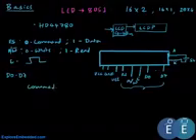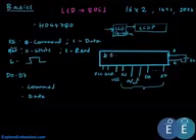All the commands that clear the display, set the cursor position, or even define how many lines a display has and how many characters it displays, are done by sending commands, and data is the actual data that we want to display on the LCD. So this would be the actual data.